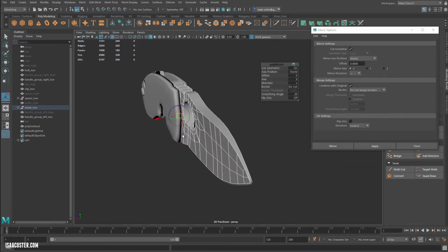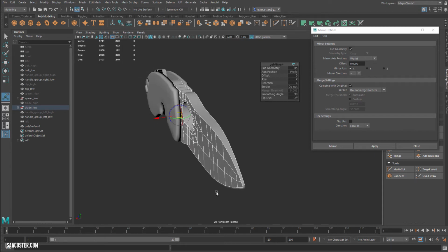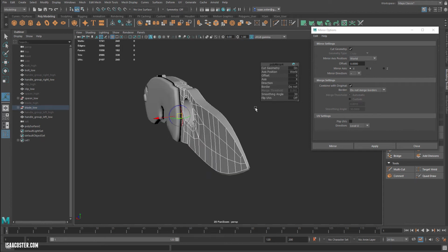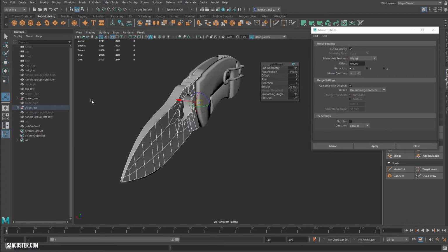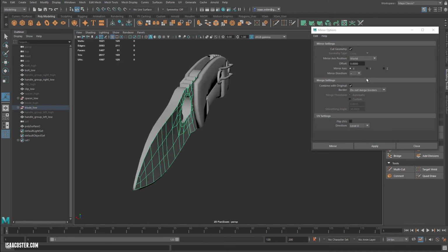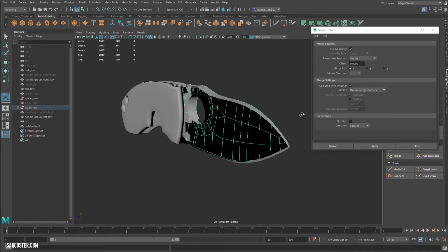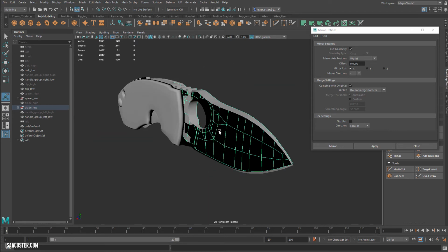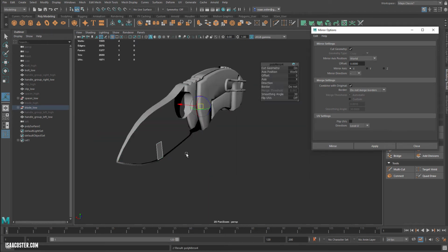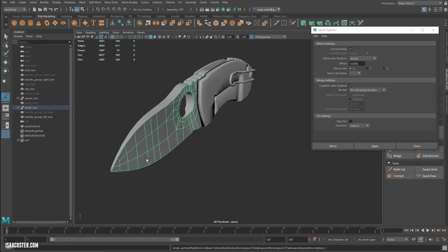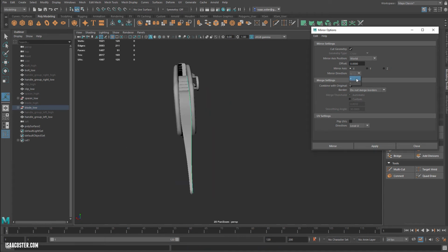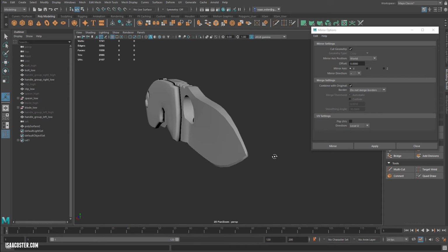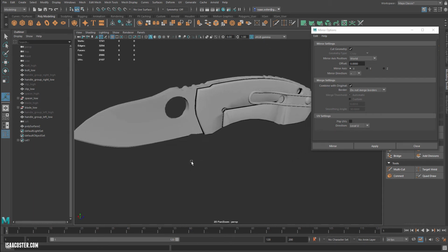There we go. So it's either going to mirror from this side to this side or from this side to this side. And if you go from a side that has no faces to a side that has some faces, it's going to want to delete all the faces, but it won't. It's like legally not allowed to. So it'll keep one. So that's basically what was going on there. So if I hit undo there and I set this to negative, it's trying to go from this side to this side, but there's nothing over here. So it does the operation that's like, oh, well, I've got to leave at least one face, but it's trying to nuke them all. So that's what's going on. So just set this to positive, and there we go. So that's fine. And here's kind of what just happened.